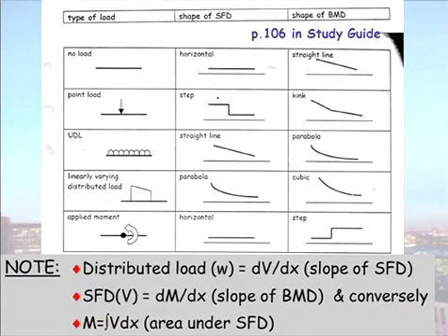So, the slope here has a big value and then it has a small value. My value of shear force here, it's a constant. So that means my corresponding bending moment is the integral of a constant, which is Cx. My shear force here has a value d. So my bending moment here is integral d, which is dx.